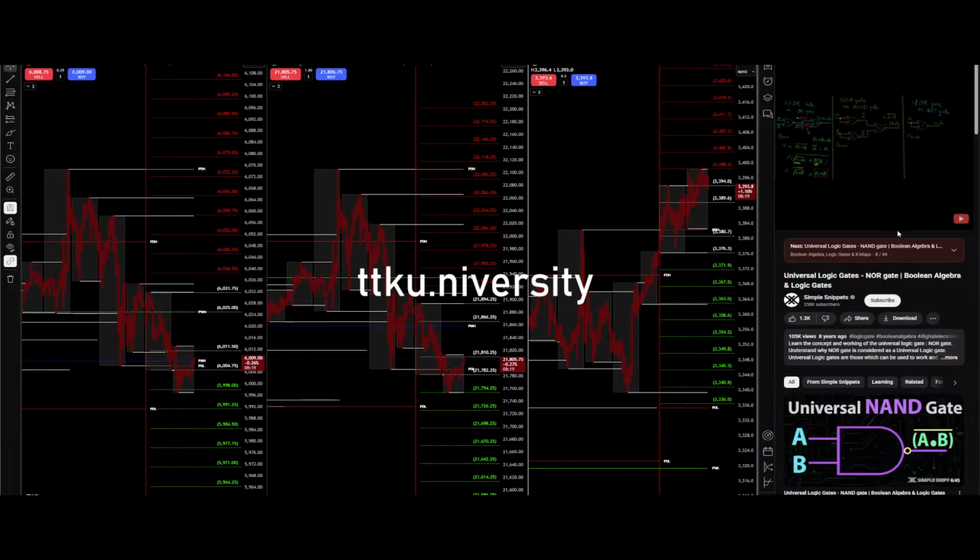So now let's see how a NOR gate can be used as an AND gate. So here you can see there are three NOR gates connected in a particular fashion. This is the first one, this is the second one, and here you can see the third one. So for the first NOR gate, we provide A as the input two times. That is, we provide A over here and A over here. So the output would be (A or A) the whole complement, which is again equal to A complement. As you can see, I have written the output over here. Similarly, we get B complement over here.